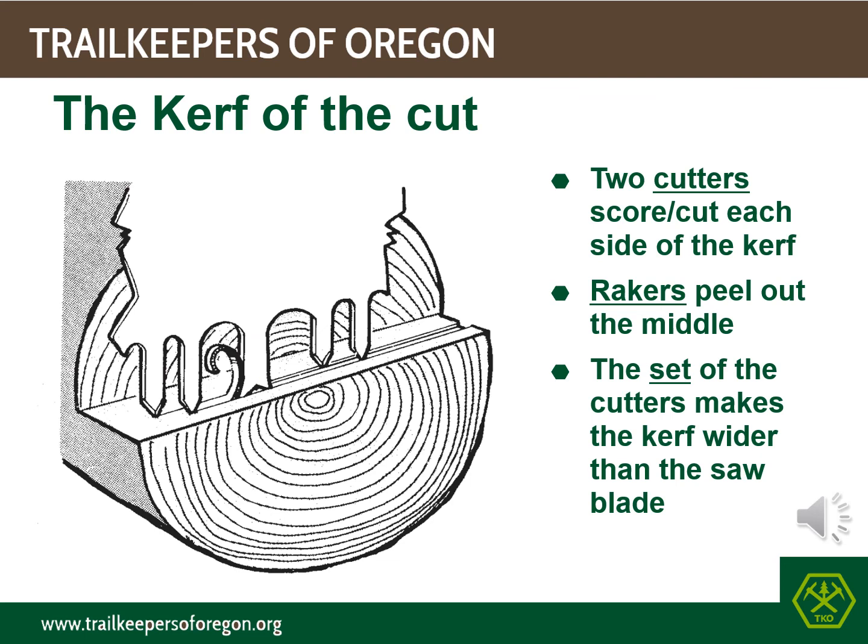The cutting action of the teeth is critical to understand what happens as the saw cuts through the log fiber. The teeth of a saw perform three basic functions. The cutters cut the wood fibers, the rakers break the cut fibers loose, and the gullets collect and remove the fibers from the kerf. The kerf is the cut slot in a log after the wood fibers have been removed.